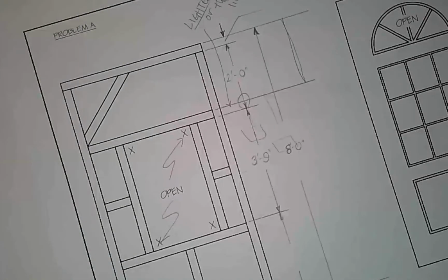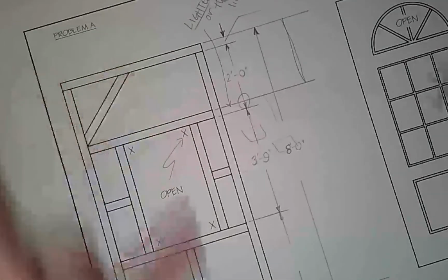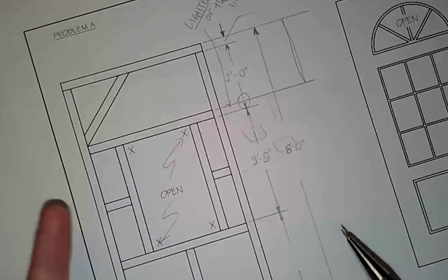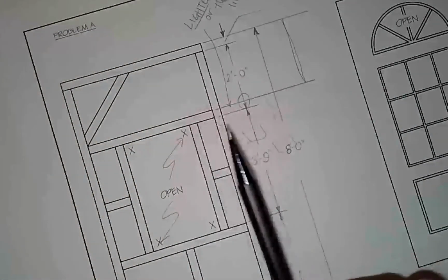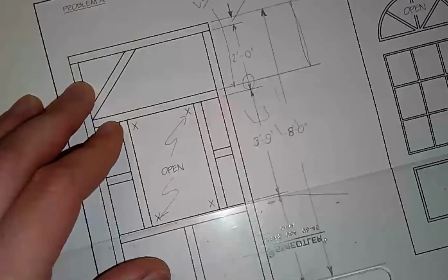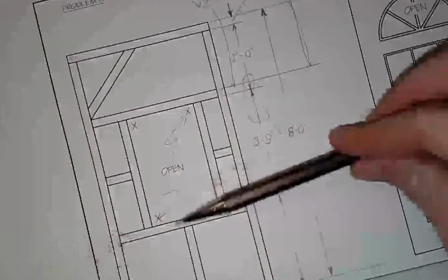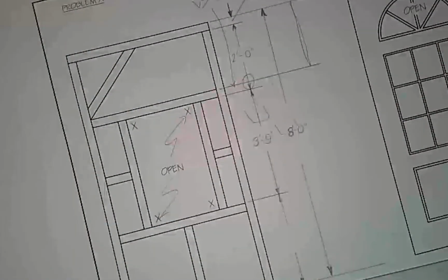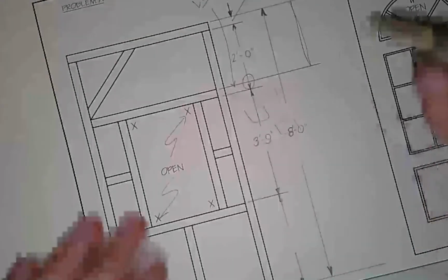If you have two views that are right next to each other, you want to place those dimensions in between those two views, right? So if these were actually the same, and they're not, if it was the same drawing, you would place that dimension in the in-between space, because that will be clearer as to what points line up. So that's like if you have your top view and your front view, then you would place, so let me just do, this is why I have the sketch pad component in life, right?